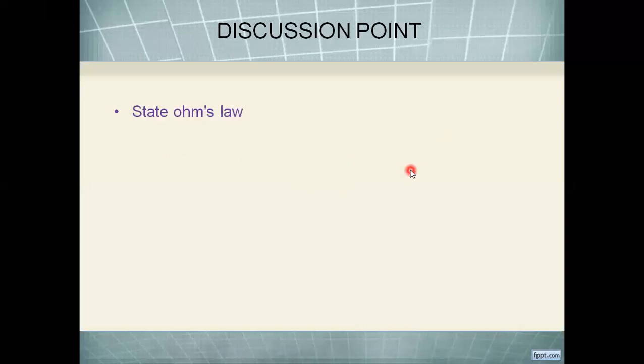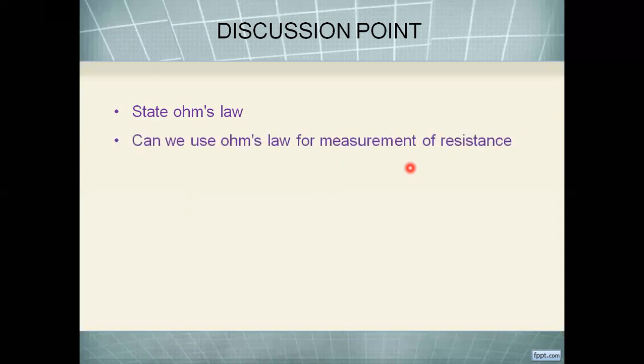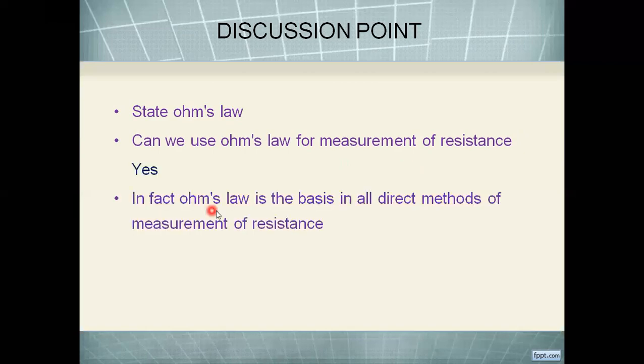So let us discuss a few points here. Can anyone state or recollect what Ohm's law is? And how can we use this? Can we use Ohm's law for measurement of resistance? The answer would be yes. In fact, Ohm's law is the basis of all direct methods of measurement of resistance.